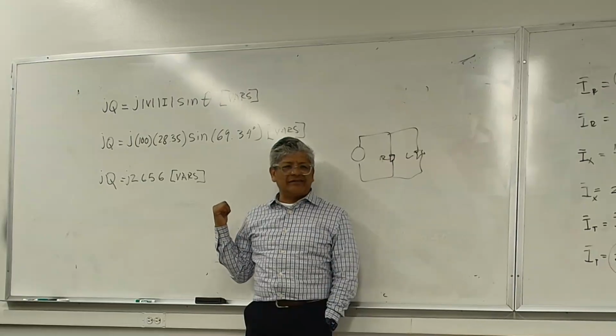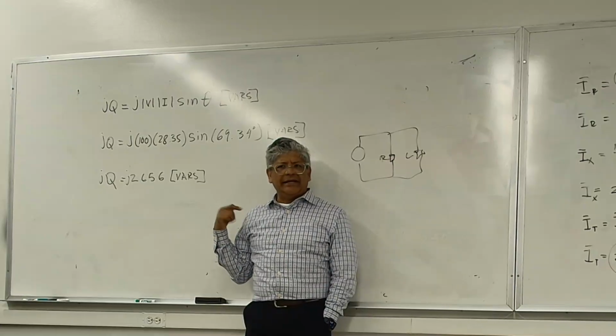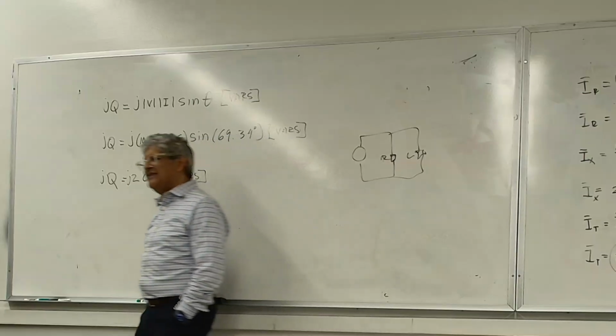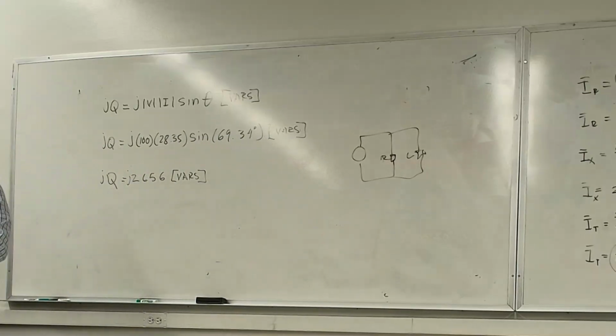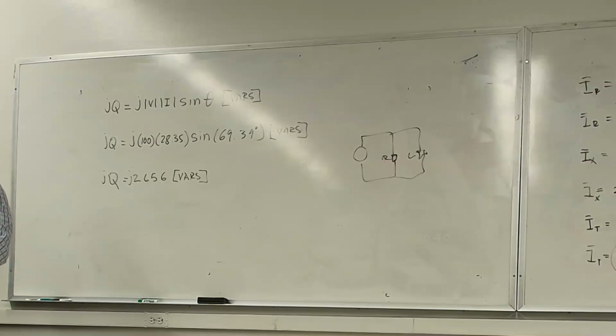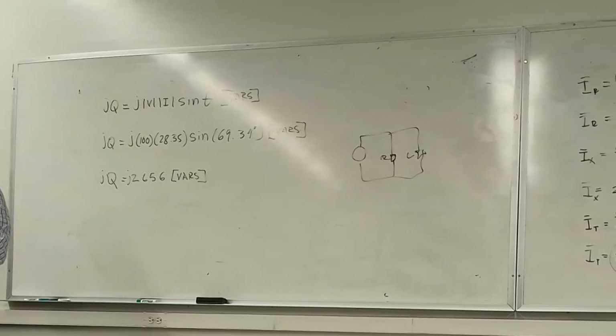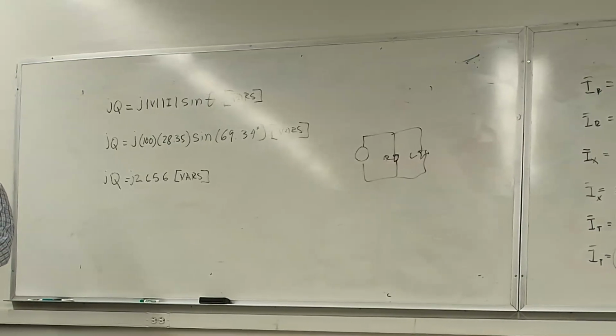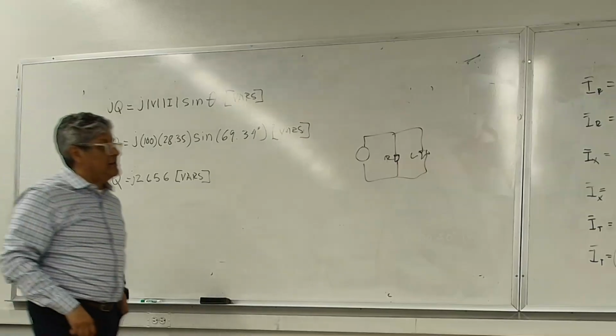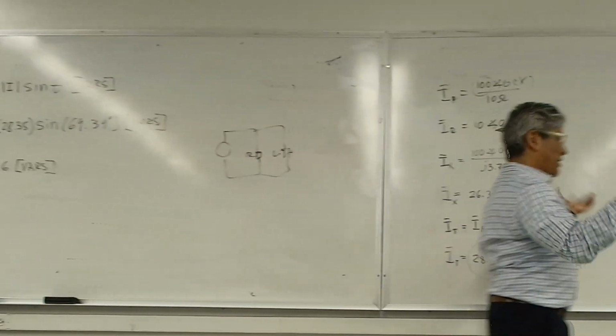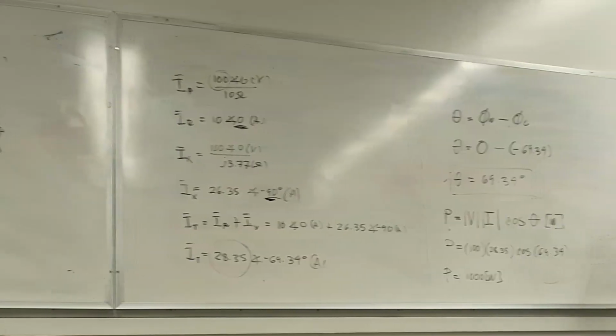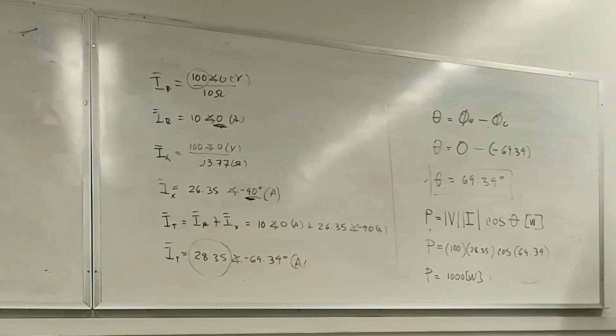Well, this load is asking you, is this what you think the utility wants? What would make them so happy with the customers? If they consume more real power. But this load is asking for more reactive power than real power. That's not a good thing. And just by looking at it, you don't even have to go any further. You can say, I know this is not good.